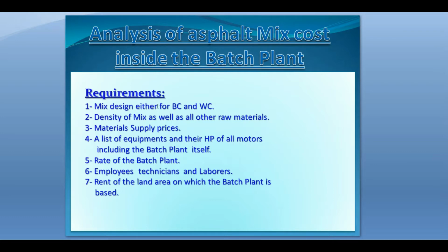Mix design, either for binder course or wearing course, we need to know the amount of each raw material inside the mix. And this can be taken or you can get it from the material engineer. Also the density of the mix, as well as all other raw materials. The material engineer has to measure the density of each raw material inside the mix. And of course, according to the design mix, he has the total density of the mix.